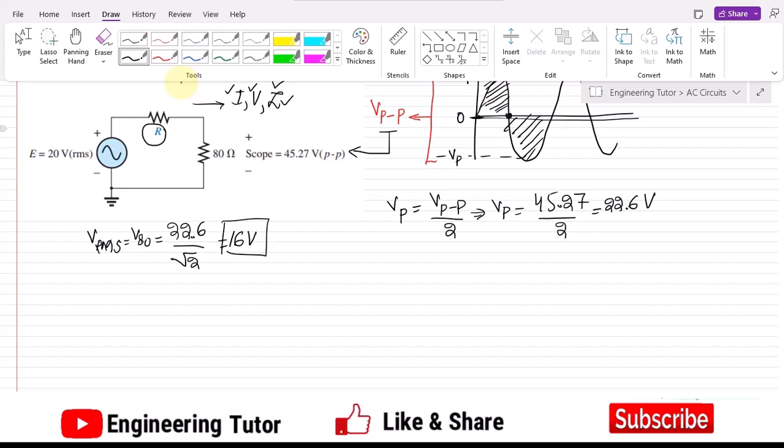As we know the voltage across this 80 ohm resistor, in order to find the value of this resistance here, we can use a trick in which the value of R will be included and all the other quantities will also be included. So we can use the voltage divider law at this resistor.